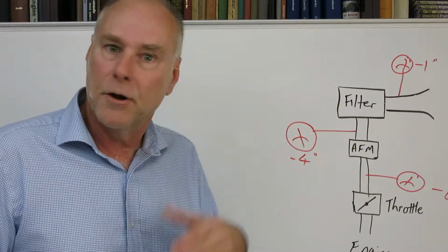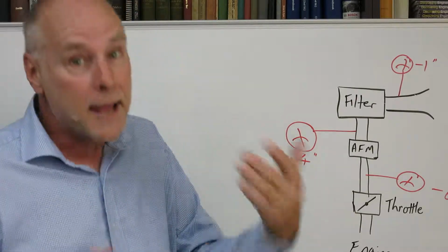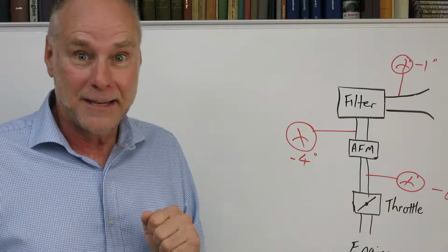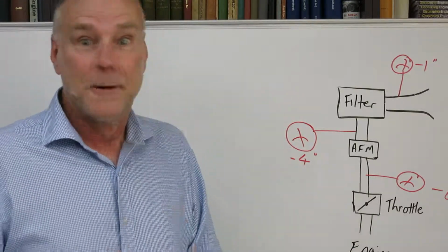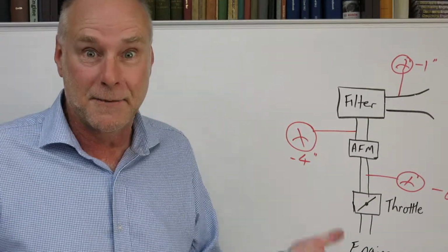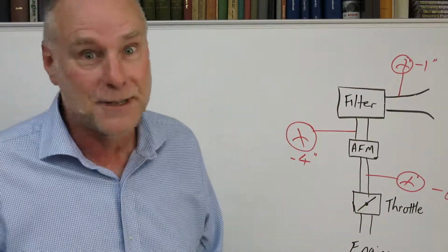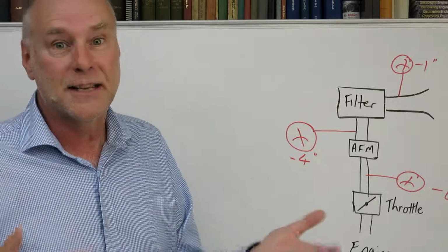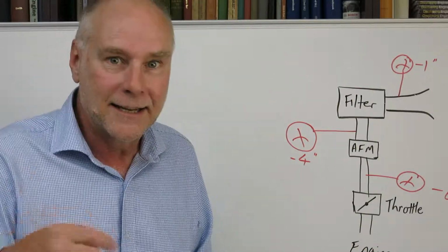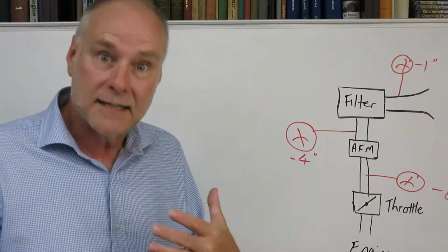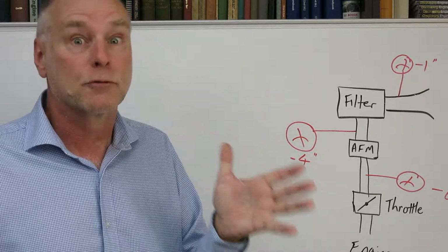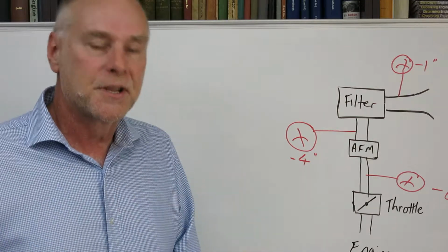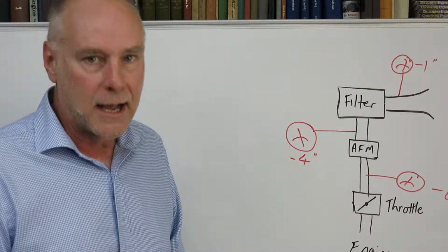On some cars, and not nearly as many as people think, the airflow meter can be causing a restriction. The old vane airflow meter, which everyone thinks is so restrictive, is actually not very restrictive at all, because at peak power it's fully open. It's just an open rectangle, the vane's right out of the way, and it's posing less restriction than a hot wire dangling in the airflow. So with these techniques you can actually measure and find out what's really going on, not what people imagine is going on, and you make changes and actually measure what those changes are.